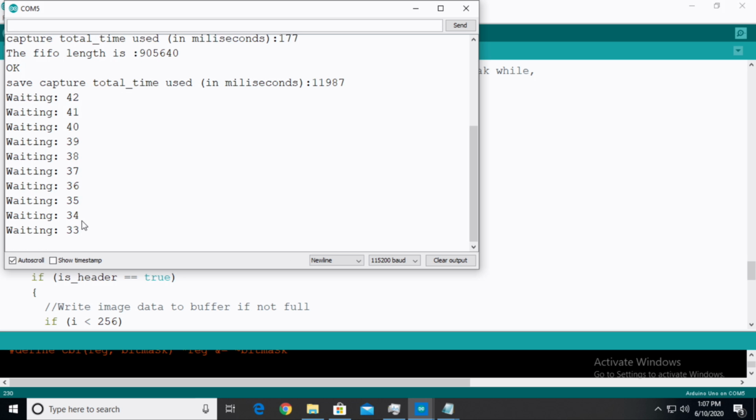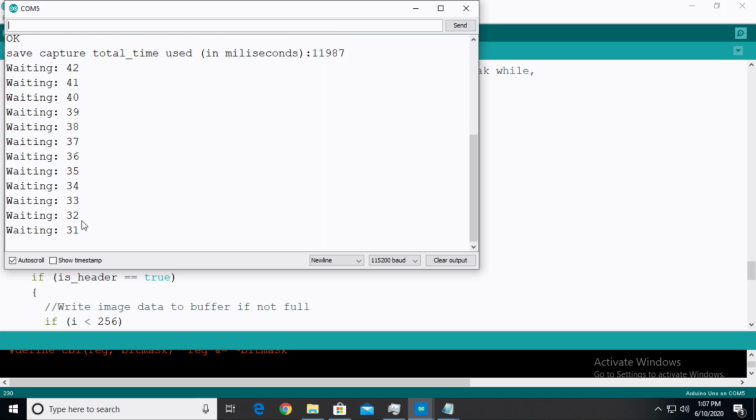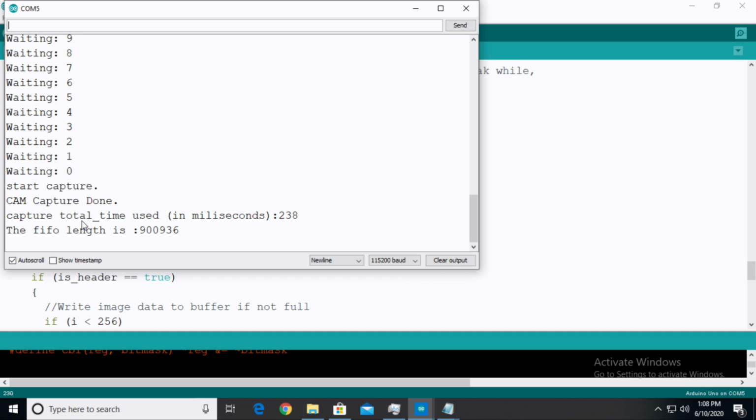Again, from a troubleshooting process, this shows you that the system hasn't locked up, the Arduino hasn't locked up, you're not getting some kind of weird problem trying to save an image file. This is just a nice little troubleshooting routine to show you that, yes, we are actually counting down. In about 15 seconds, it is going to take another picture. As I sit here waiting, it's going to count down, count down, and then when the time is above 60, it's going to start the capture again, and so it is now taking a picture.